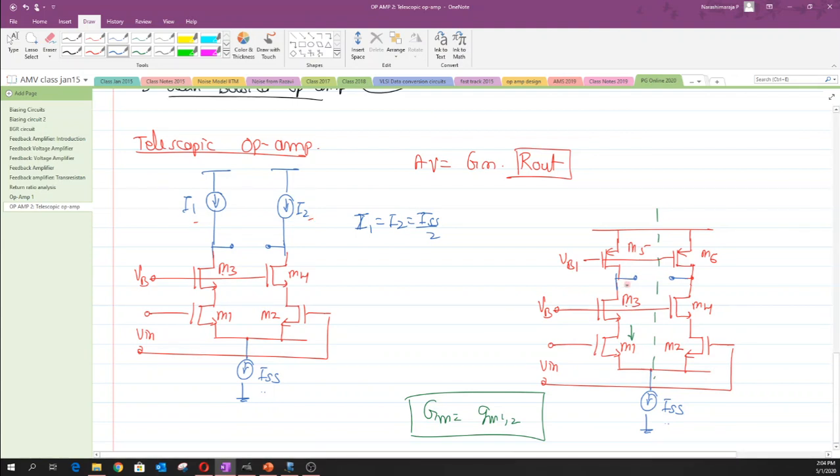The reason is that when we look down, this transistor M1 gives us an impedance value equal to RO1, and when it is seen through the drain of this M3, it gets magnified by the intrinsic gain of M3, and the value can be written as GM3 RO3 magnifying this factor of RO1. That is the impedance that one would have when we look down across the drain of this M3.